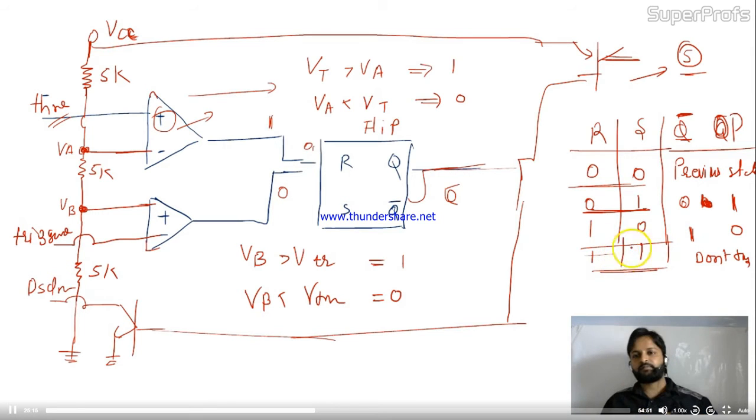Okay, friends. So based on this, the circuit will work when you give 1 over here. This transistor, let's call it Q3, will be on. When it is on, the entire thing will discharge now. The circuit will complete, and the entire thing will discharge. When it is 0, it will be in cutoff. In the cutoff region, nothing will happen. Reset will happen then. Like this, the circuit will work.